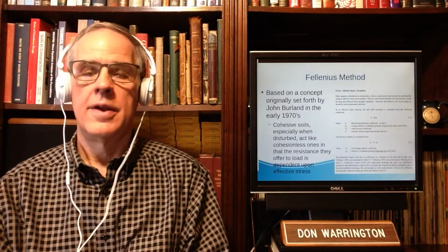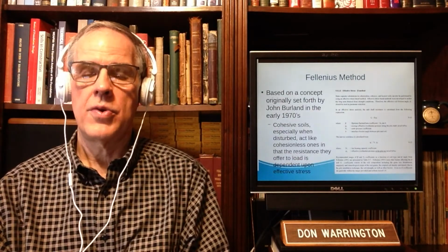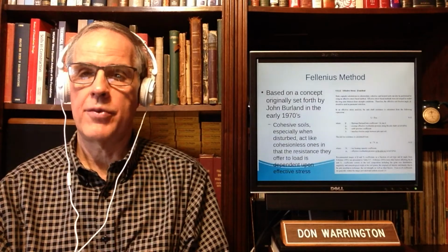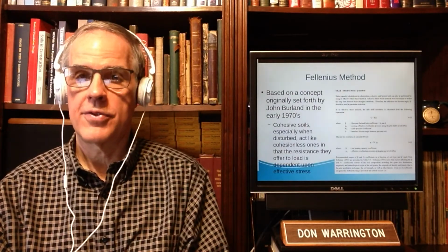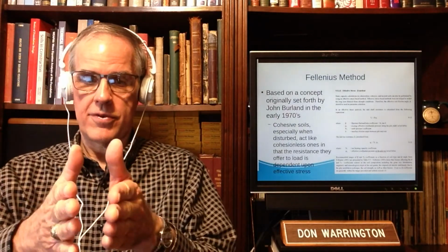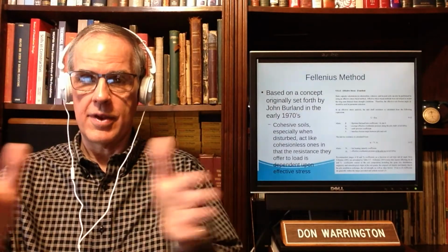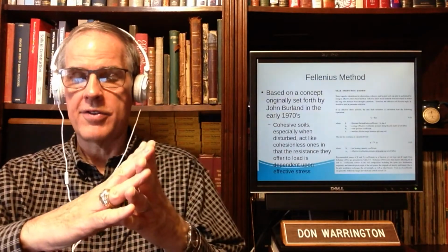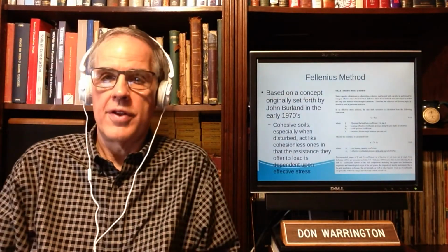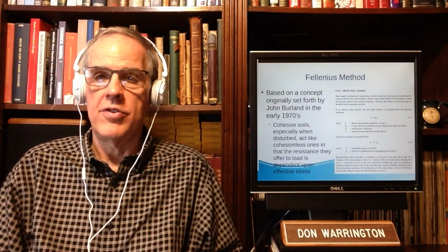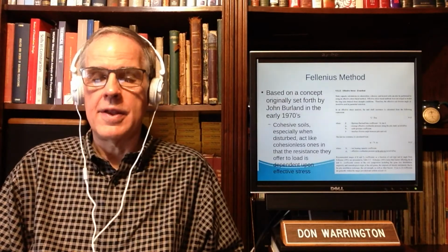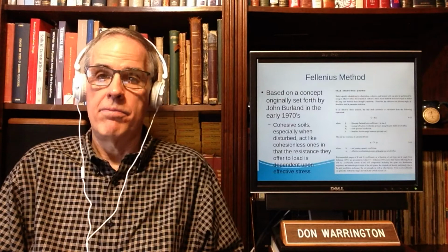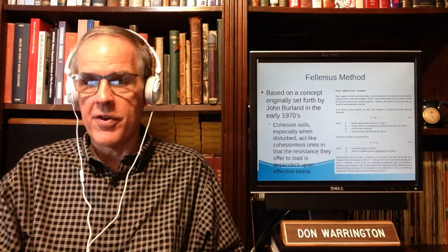On the other hand, in sands, as with any other cohesionless soil, the soil does not develop strength unless it is being compressed by the effective stress. The effective stress produces pressure that acts against the shaft of the pile, and therefore the frictional resistance is governed by the effective stress. It's basically equal to beta times the effective stress. Thus they're called beta methods, and we can break that down further.